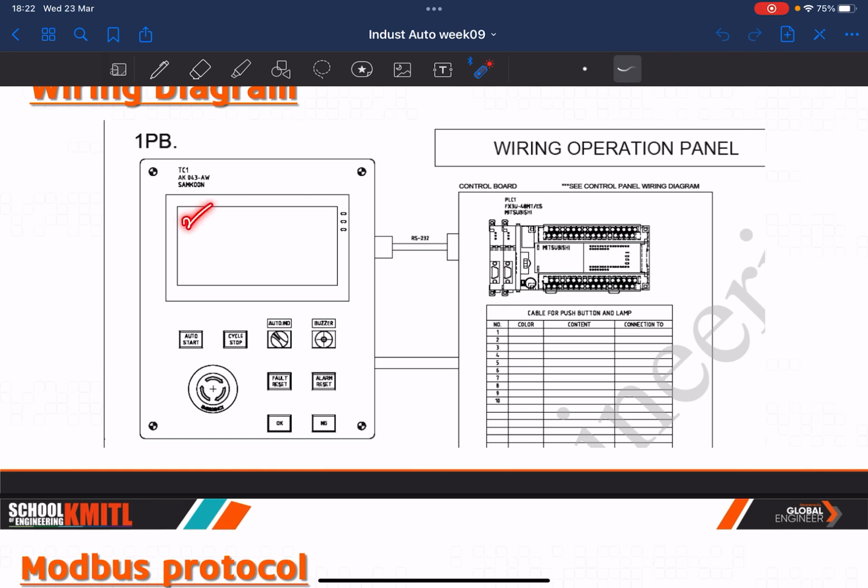When you turn this on, this coil will change its state to 1 or something like that. Or you have some data inside, like 300 something, and you would like to show it here, so you connect it with D100 or something, and then you capture the detail inside and show it at this position. This is how the HMI works to connect to the PLC.